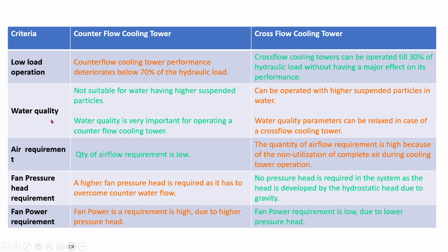Then water quality. In the counter flow, water quality should be very clean. It is not suitable for suspended material, because if suspended material is there, heat exchange will be very difficult, and water quality is very important for operating a counter flow cooling tower. But the cross flow can operate with higher suspended particles, and water quality parameters can be relaxed.